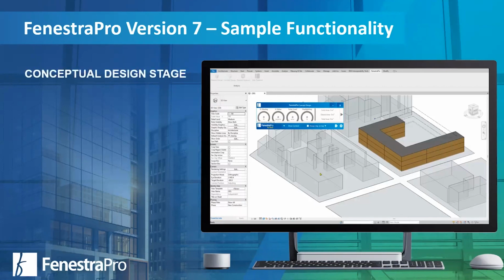Now, as I'm sure you're aware, within conceptual design within Revit, the walls are effectively paper thin. When you create windows or openings, they're referred to as notional openings. So the Revit model doesn't store the data. The data is stored in the application, whereby it can be managed through the application as you start to establish the key things that we talked about in terms of the passive solar heat gain, natural daylight, and of